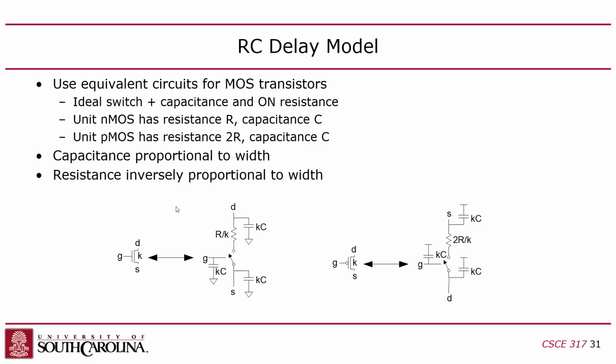But remember that the PMOS substrate is going to be connected to VDD to get that negative voltage on the gate when you put a 0 in. Substrate's also VDD, right? Which means I've got VDD here and VDD here, which means I have a capacitor, but both sides are connected to VDD, so I don't care.